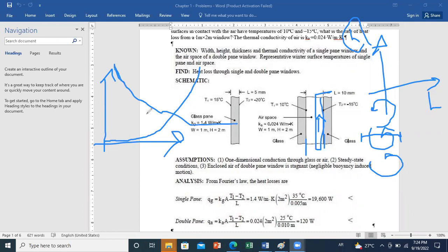Now, when you sum conduction and convection, because at the end you will have both processes, you want both to not be at a very large level. You can optimize the total heat transfer. When you draw the total heat transfer, you will get an optimal length for which this heat transfer is minimized. So you will work with this optimal length.